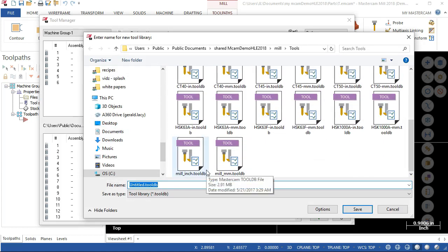Let's go with the My Tools, or more specifically to a machine. I would probably set this up. I'm going to run the Haas tool room mill, and then I can set the RPMs and start to get a little more refined as to 4,000 RPM max, 7,500 max RPM, 10,000, 12,000, whatever we're working with.